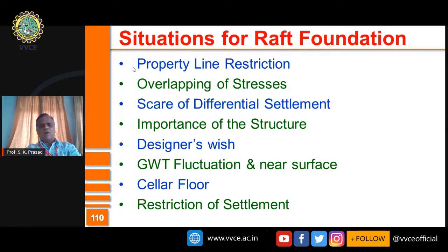So we talked about the first 5 issues and said that you go for combined footing instead of isolated footing on these 5 issues. I'm not going to repeat the same. Okay. In addition, these are the other 3 additional issues which will make a designer go for higher order foundation like raft foundation. One is groundwater table fluctuation.